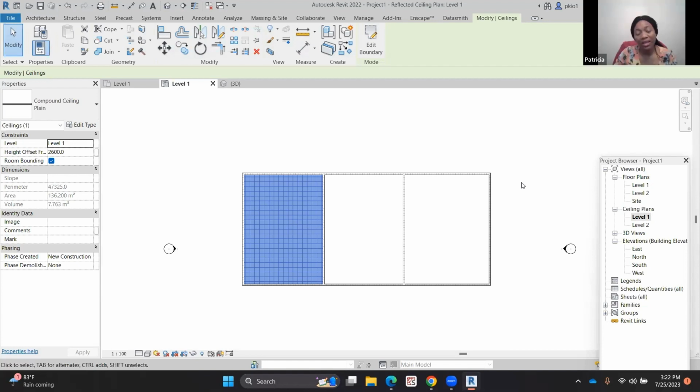Yes, so for that other third option, the curved ceiling, the model in place will be most useful, where you would have the flat parts and then you would have the edges of the ceiling. You model that with those sweeps, just like the way you do your parapets. So you have to do that inside each room. There are a lot of videos for ceilings on YouTube, but the main thing is to know how the thing works, and then we can go complex with it, and you can make the ceilings at different heights too.